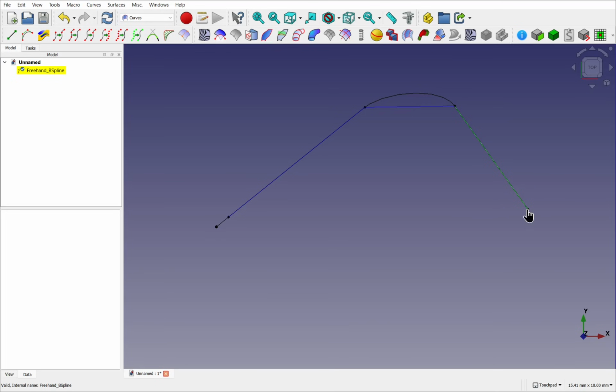We can move the point or the segment, and let's click on the point and move that. And you can see how that segment is behind there now. To unset, we just click on the line that clicks on the segment behind and hit L again. We get the segment back, and if I hover over the point, we can see that curvature in there.